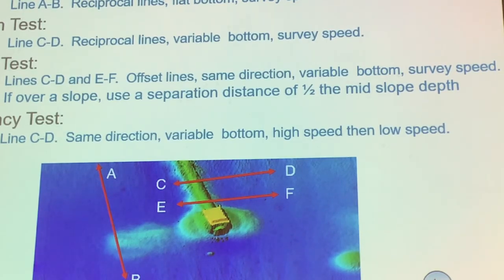So it's better to, okay, let's say you want to do a 5 days survey. On the first day, find a good patch test area first. Locate and record the location of the patch test area. So for the other days, when you do the patch test, you can come to the same place and do the patch test and then carry on with the survey.